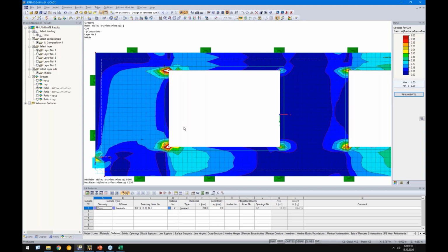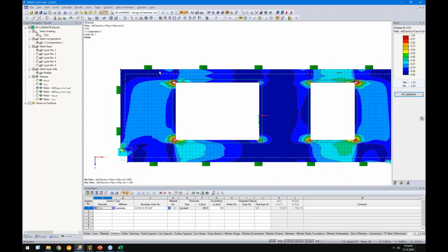Unfortunately, we have no possibility in Timber to distribute any stresses to fix the singularities, or to distribute the stresses with a plastic analysis, so a nonlinear plastic analysis, since we use only a linear elastic material behavior in Timber, which is actually common. So there is no real way to check it also for timber.